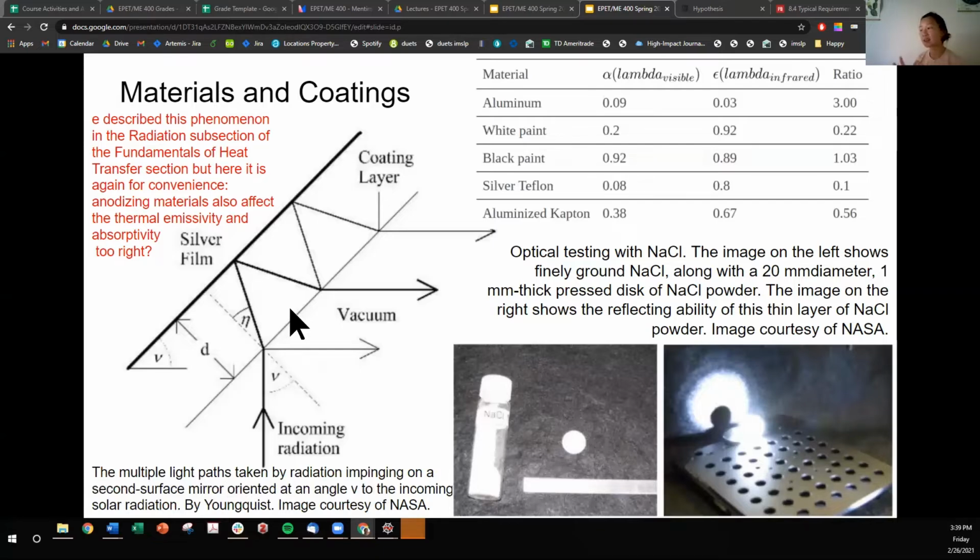The inside of the spacecraft can get to about 100 degrees Kelvin, which is negative 173 Celsius. Don't quote me on the exact number, but cryogenic is around that temperature range. That's incredible. That's a passive solution. So that shows you the power of using a state-of-the-art surface coating.